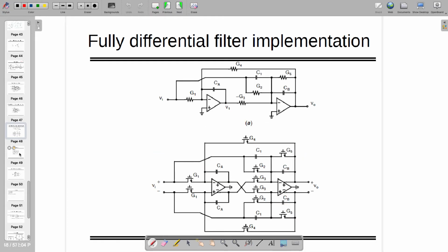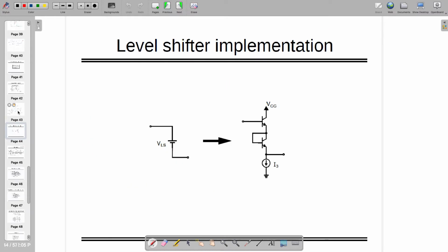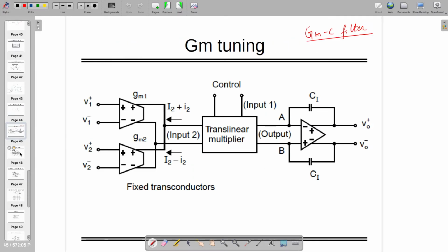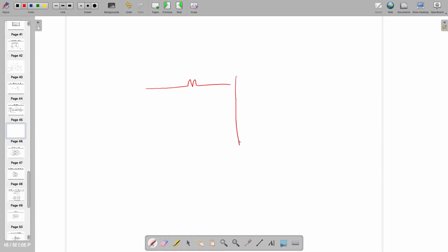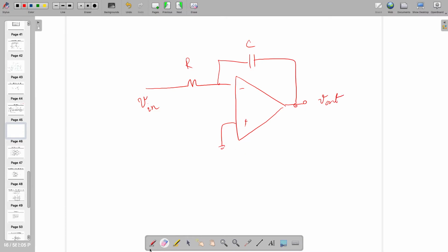So that's not good, okay, where did it go. What I meant to say, let's assume that you are designing a simple circuit like this. If you are designing this and this is an op amp, the gain is moving around the corners, right? All corners. But you made some budget and you kept it within the budget. For all corners, slow, slow, fast, all five corners with temperature, with voltage, you checked everything. And you said, okay, this is giving you what you wanted at the worst corner. And other corners, it's good.